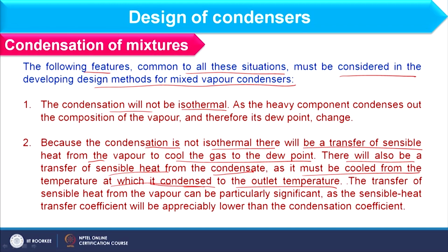The transfer of sensible heat from the vapor can be particularly significant, as the sensible heat transfer coefficient will be appreciably lower than the condensation coefficient. So, in this way we should compare the coefficient of condensation as well as sensible heat transfer, and obviously the condensation coefficient is much higher than the sensible heat transfer coefficient, right.